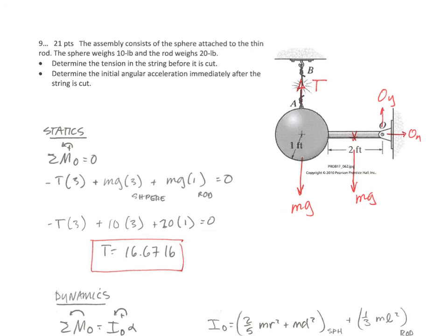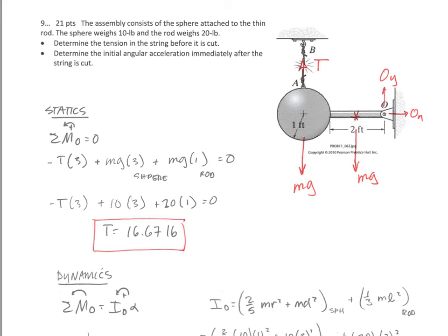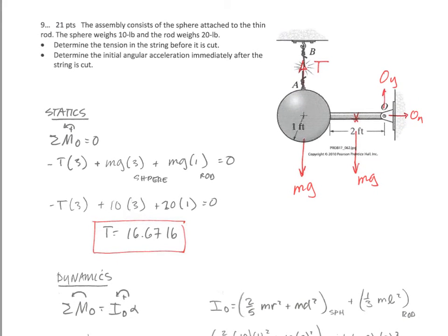All right, this next one, worth a little bit more. This was the statics problem to start with. What is the tension in this thing before you let it go? A lot of people missed that. But basically, there's a reaction here at O, both in the y and in the x direction. And the sum of the moments about O at the statics part is equal to zero. You got that plus that minus this times that length, and you get tension is equal to 16.7.